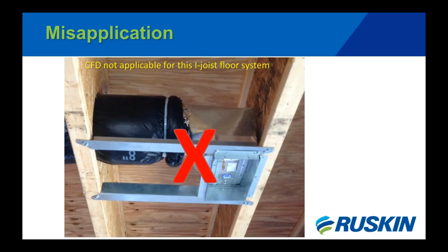And the last thing is, should engineers be noting these assembly numbers on the CFD schedule, in the spec? Absolutely. Anytime you have that type of information to put in there, it's going to shorten the process of trying to figure out what can be done, what's right, what's wrong. So yes, we would definitely say that that's only helpful, because the first question we ask is the ceiling design number. Usually people don't know it up front. They have to go research that out. So the more information shown on the schedules is only going to help. So we would absolutely promote that.